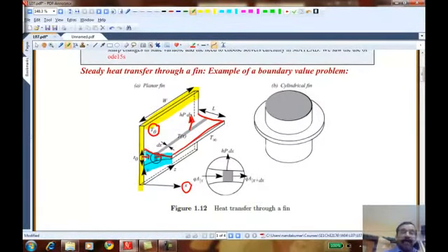And then this exposed surface is at a higher temperature than the room temperature. So again, the energy will be transferred by convection. If the air is not moving, the air molecules are still free to move. The moment you heat them up, they become lighter compared to the neighboring air molecules, and gravity acts on them and pulls them up. So that is called a natural convection mechanism. Or if you blow a fan, you know at what rate you're blowing air, so that's called a forced convection mechanism. So there are models to capture how much heat is being transferred by the convection mechanism.